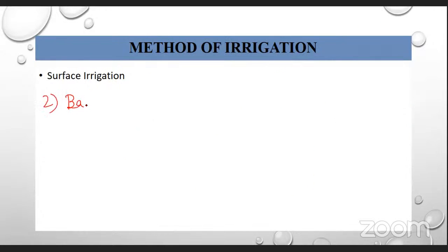basin flooding. Okay, so this basin flooding means small level plots surrounded by low earth dikes, which are also known as checks. And this is the check basin, which we usually call it. And then in basin we have the first one.